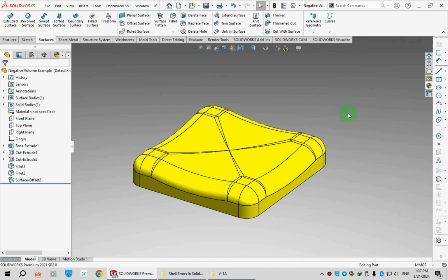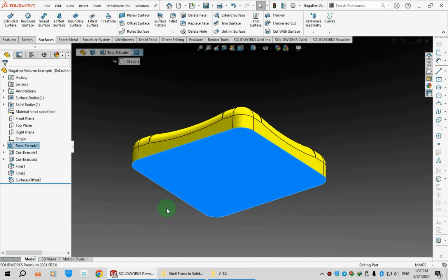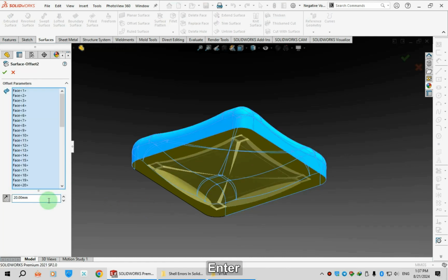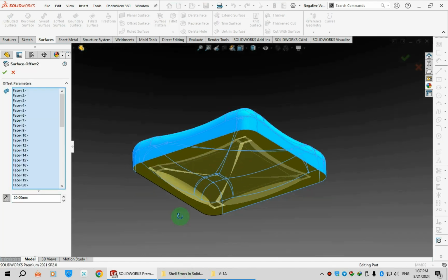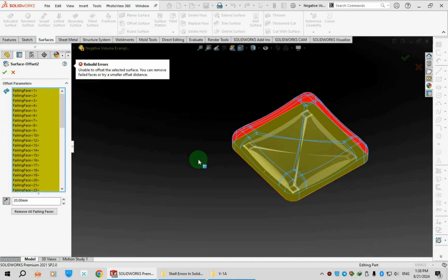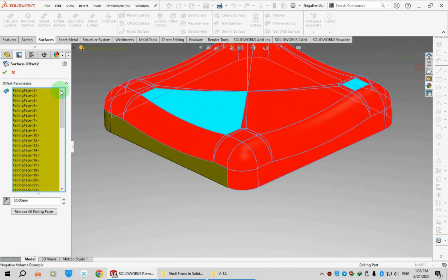Every inner shell is like an offset surface, normal to the original reference at each point, and filled as a solid feature. So if the thickness value is greater than the radius of some point somewhere on the object, it's not possible to have such geometry.